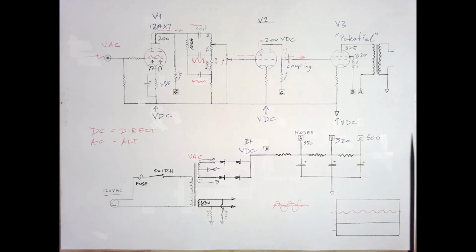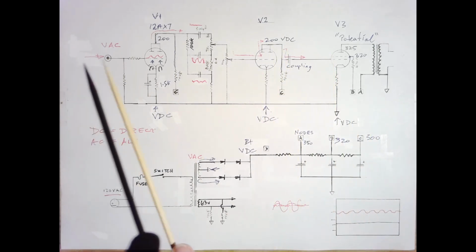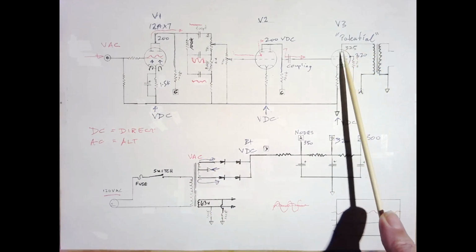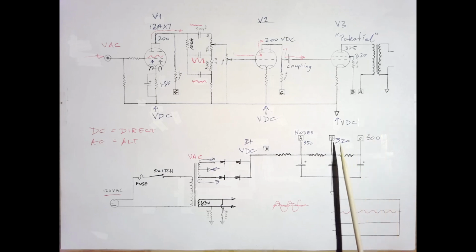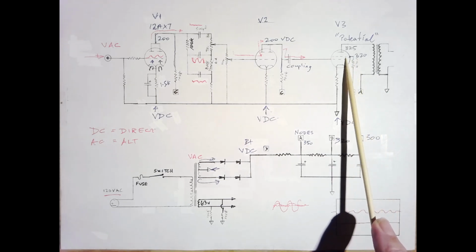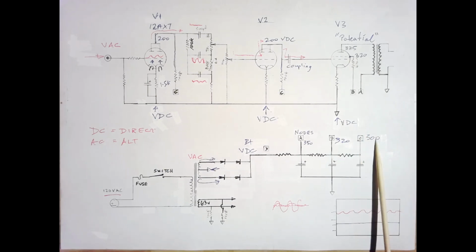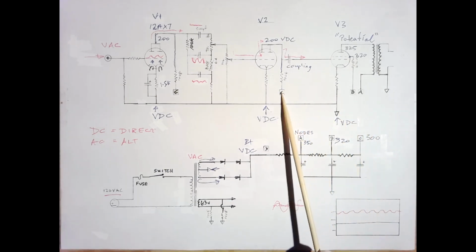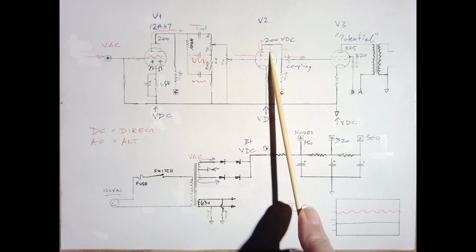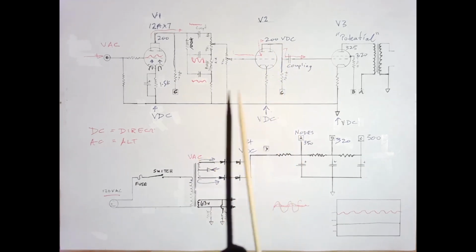You could have more depending on your amp, and you could have a much more complicated amp design than this. But we have a potential sitting there. And then on node B we have a potential coming up and sitting on our screen grid. And then through our C node we have a potential coming up through a 100k resistor and coming up and sitting on our plates. And this is also being powered by the C node here.